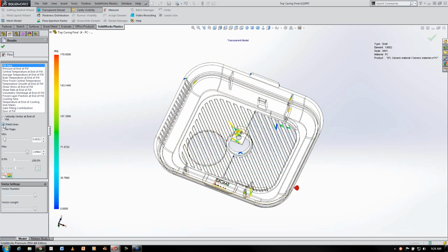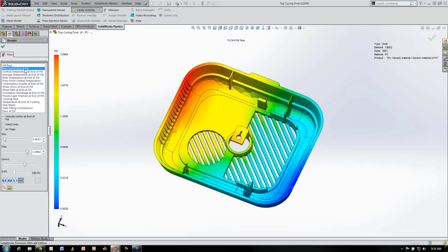Let's turn on the weld line plot, and that actually looks much, much better. The circular cutout where the grill ribs go across, there are no weld lines. And then we just have a few weld lines on the rectangular ribs, just 3 pieces of geometry. So considering where we came from, that's a very considerable improvement. Is it the best that we could do? I don't know. That's what running further studies in plastics could help us determine. So that looks pretty good compared to where we came.